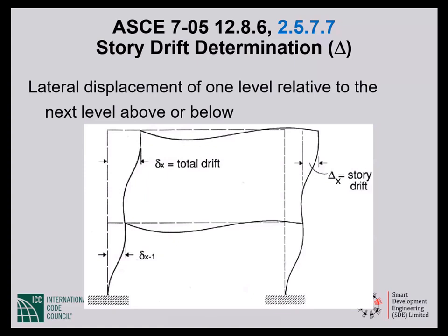We will start with what is commonly referred to as drift check, which is an integral part of seismic design by ASCE 7-05 or BNBC 2020. The interstory drift have to be kept within tolerable limits.